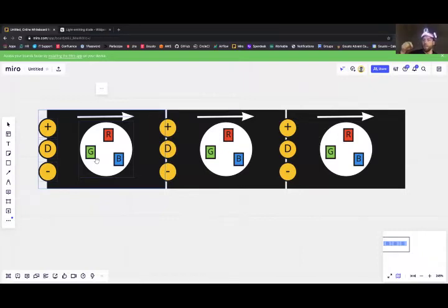So a pick and place machine, which is a robot, typically in China, in Shenzhen, China, where a lot of these things are manufactured, will take these little surface mount components, those square packages, place them onto a printed circuit board, apply some solder paste, which will ultimately melt and fuse the connections between the input pins on this surface mount component to the printed circuit board so that the circuit can be completed and used.